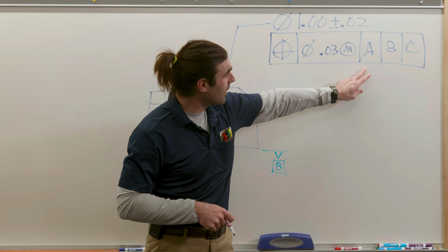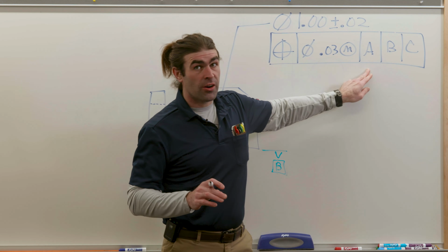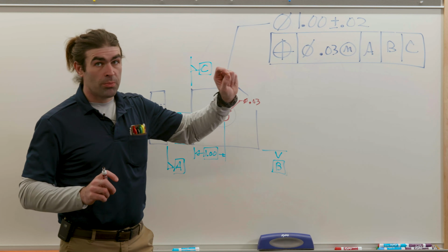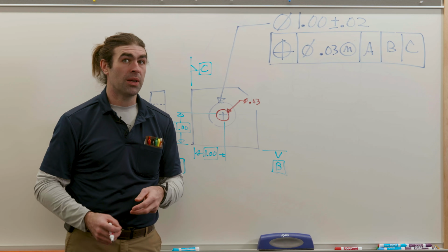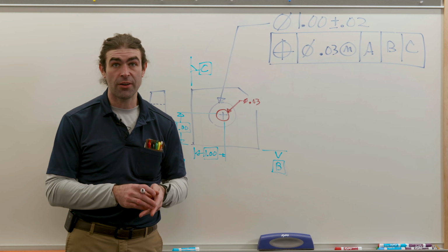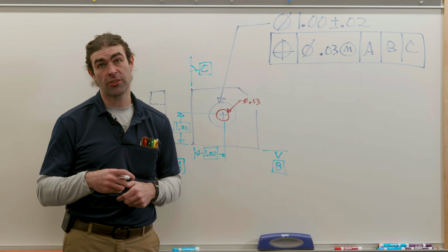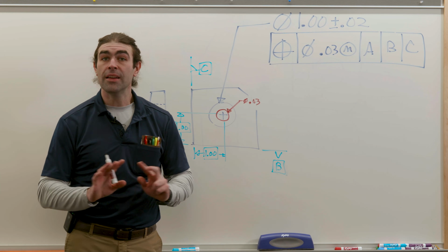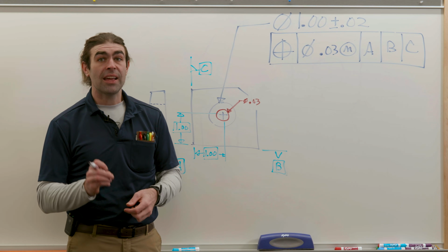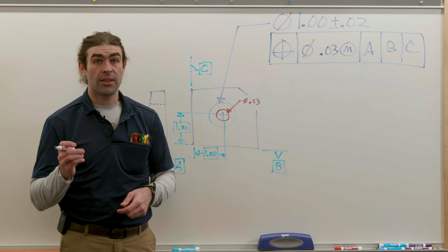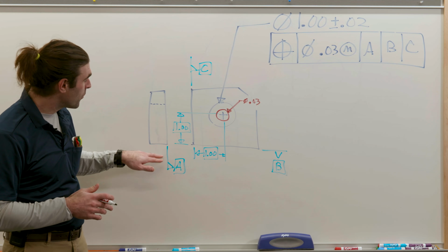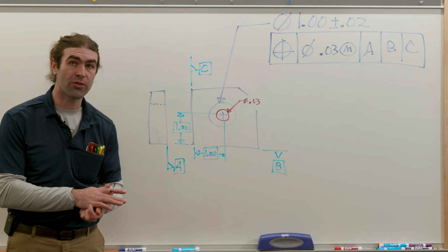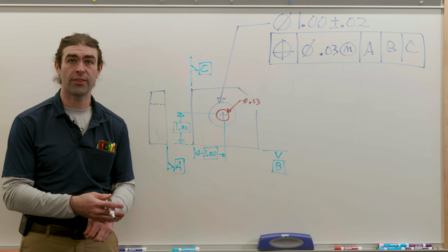Next, now this is important, are datum references. Most of the time, they will be written A, B, C because it's a popular choice for designers. It makes it easy to read drawings because people are used to seeing it. It does not have to be A, B, C. It's in the order that the part is set up for inspection. So datum A should be a mating surface, the largest and most important mating surface.